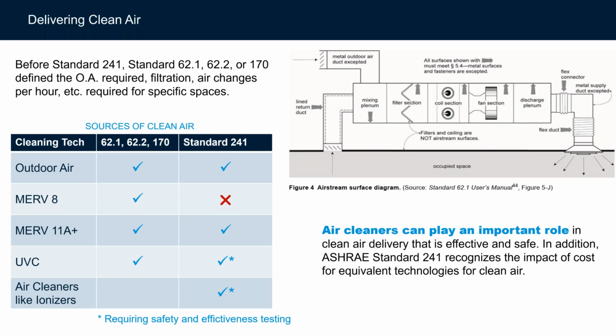UVC is still approved. However, the UVC OEMs will now have to demonstrate that they meet the safety and effectiveness testing, leveraging the normative Appendix A that I've already laid out. And then obviously all other air cleaners, such as ionizers, would have to also meet that same effectiveness testing in Appendix A.